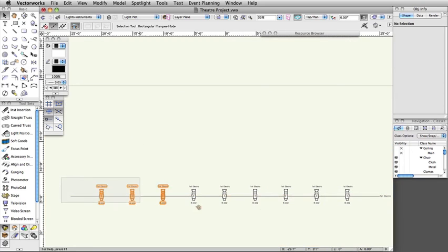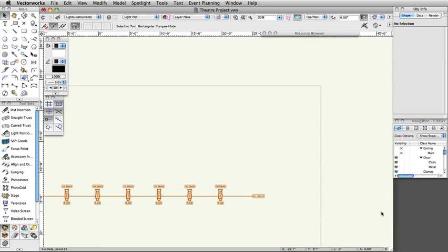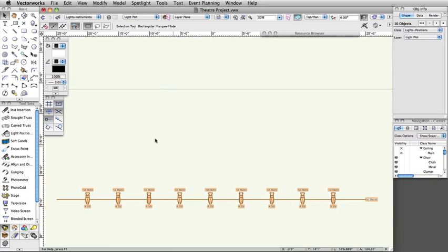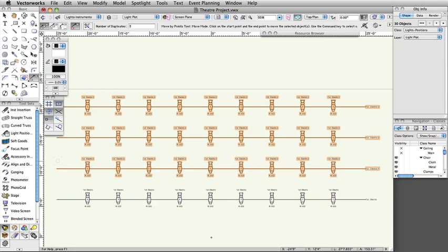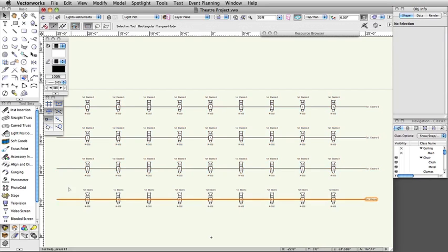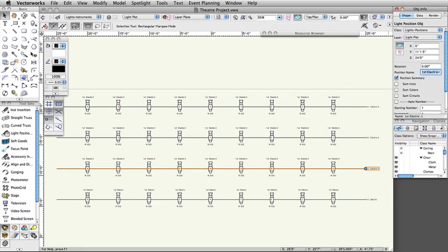Select the first electric and all of the lights. Activate the Move by Points tool in the basic palette. In the toolbar, set the tool modes to Move and Object Retention, and set the number of duplicates to 3. Click once on the stage right end of the first electric. Move your cursor up. Press Tab to enter the floating data bar. Set X to 5 feet, and press Enter or Return twice. Adjust the position names in the Object Info palette to display 2nd through 4th electrics.